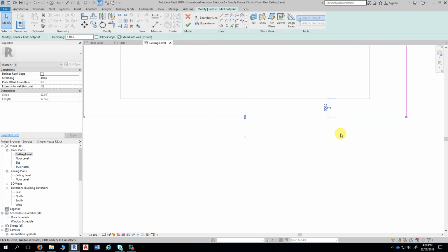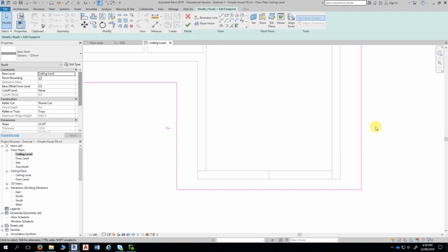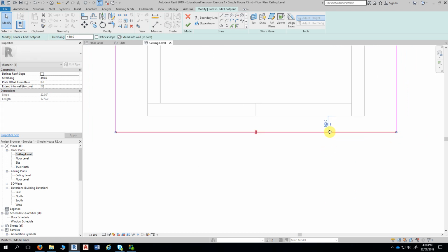I thought 450 now. Is it? Because it's a 300, but because we have sticks that extend into the wall. No, the roof's not pitching from there. The roof's pitching 300 from the outside. Have a look at your 3D model. Basically the roof is not pitching from that core, it's pitching from those side walls up. That's why, it's measured from the outside of the wall to the fascia. Yeah, that's correct. So that temporary dimension is actually measuring from the fascia to the wall,